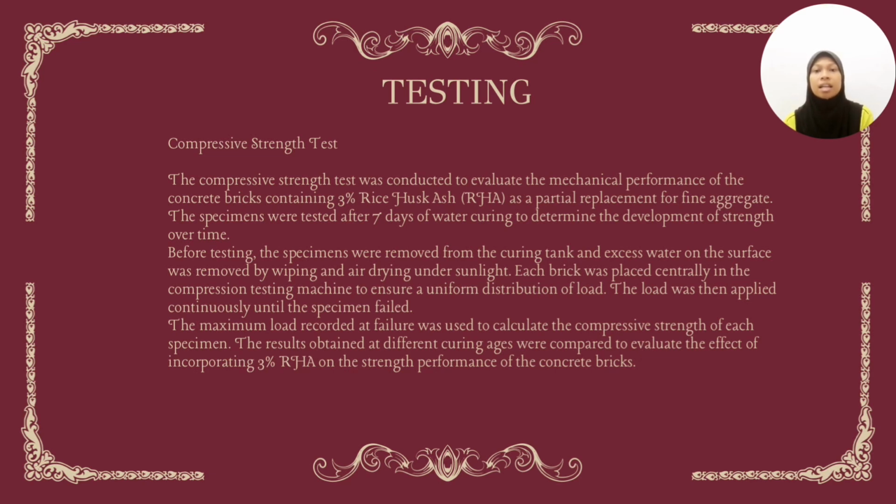air drying under sunlight. Each brick was placed centrally in the compressive testing machine to ensure a uniform distribution of load. The load was then applied continuously until the specimen failed. The maximum load recorded was used to calculate the compressive strength of each specimen. The results obtained at different grades were compared to evaluate the effect of incorporating 3% RHA on the strength performance.